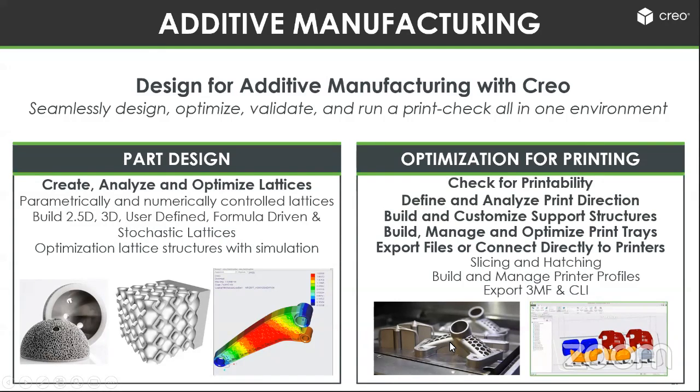Now in the shape of the geometry here, earlier this particular shape of the geometry could not be predicted, but with additive manufacturing we can predict with the help of the software what the design should be to maintain the strength of the material with less quantity, less weight of the material. That's a direct saving on cost to manufacture that particular component. So that way optimization of the model is possible with additive manufacturing.